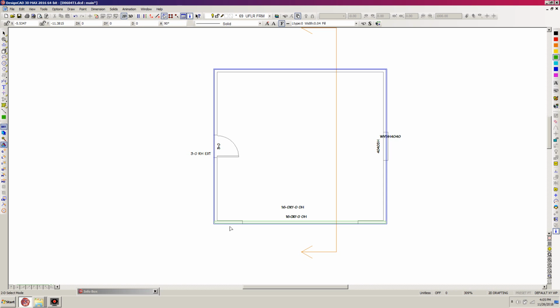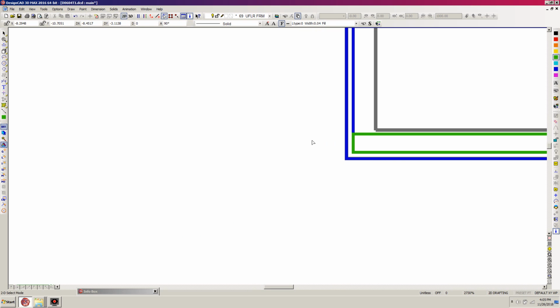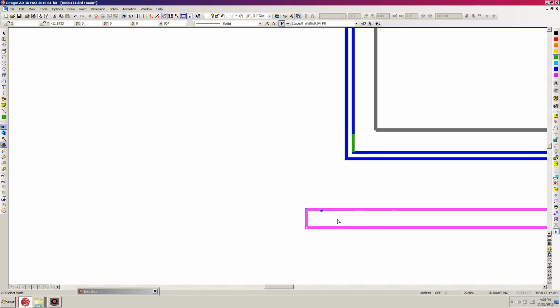Now these joists are going to be on 16-inch centers, and of course this one's not exactly there. So I'm going to hit Z for zoom, and set a little handle on it. I'm going to move this joist out right now. M for move, and get rid of that previous mistake by hitting delete. I'm going to select this joist by getting close to this end and hit Control K. That both selected the joist and, because it was Control K, set the handle at the center of that web.